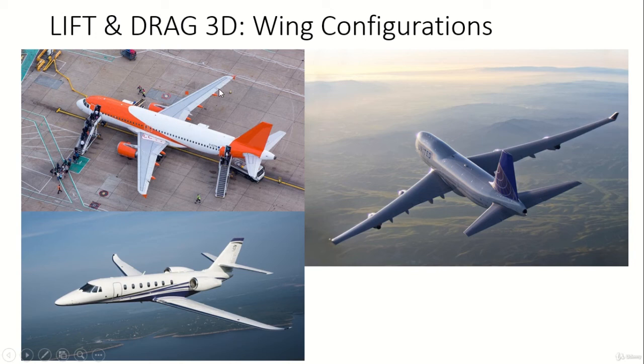You can imagine that the wing is providing lift, so this lift will be structurally connected to the fuselage only on this surface over here, so this surface has to withstand a lot of stresses, which is what we discussed before. So this is why in this configuration there's more surface of contact, like this.